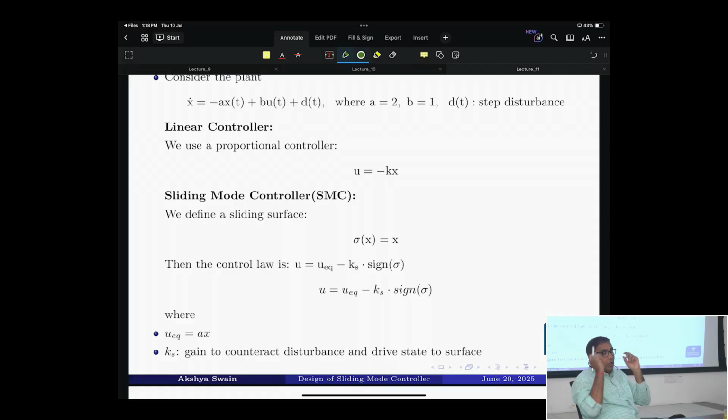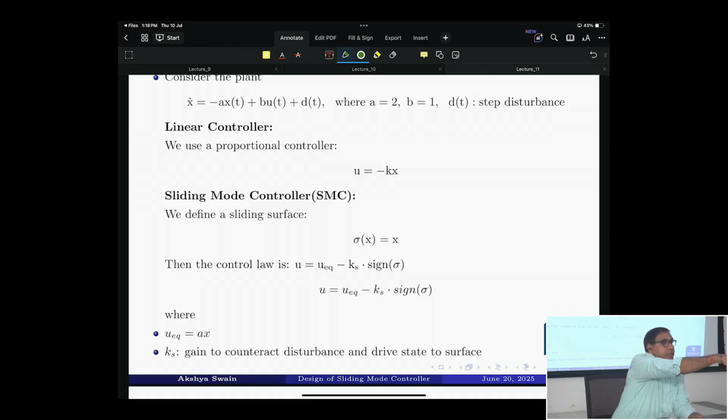So what is the chattering in sliding mode control? Chattering happens because of the nonlinear control law, see, that's the point. Again, the same analogy. You should understand the concept, always think of the analogy. You are in this surface. Chattering will come because of the nonlinear part of the control law, right? So that is one person who wants to go out of the room. So what will the control law do? It will push him. In a normal case, what will you see? He wants to go out. Then you will push him. Then he will shout, or he will not shout. He will ask, why are you pushing me? The same system also tells the same thing. It will chatter.